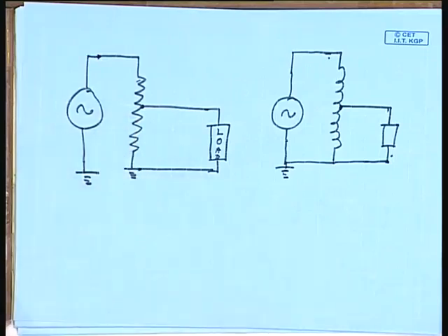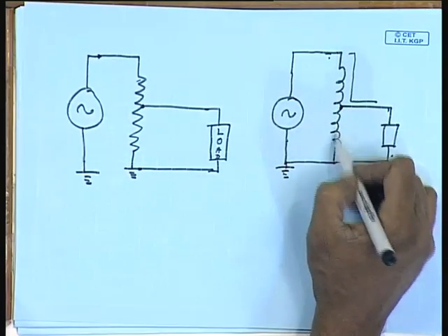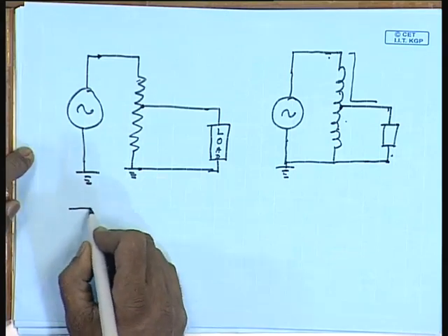Here, unlike a resistive potential divider, the power transfer takes place both conductively through this path and also by magnetic induction, because of flux coupling between the two sections of the winding. This is the principle of the transformer, and since magnetic coupling does not require physical connection between the windings, it is entirely possible to separate this auto transformer arrangement into two different windings. For example, it will then look like this.